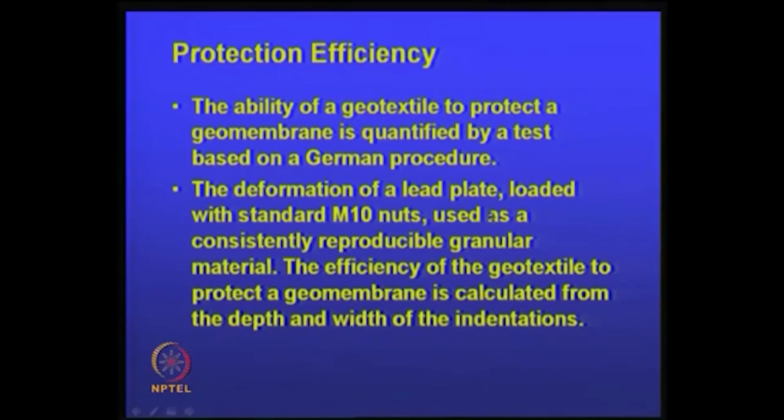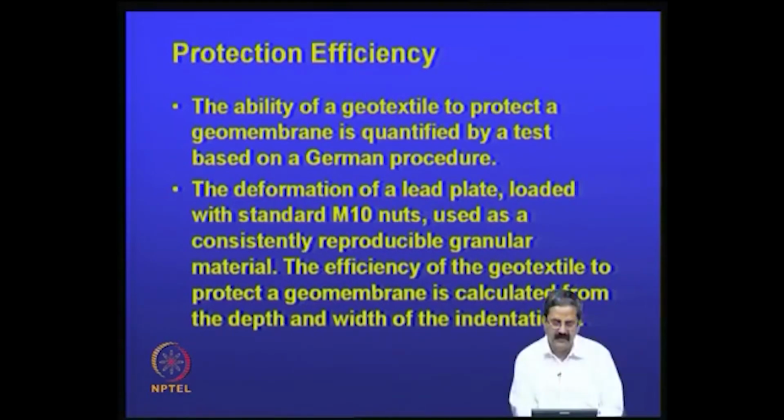Then there is another test called protection efficiency. Protection efficiency is the ability of the geotextile to protect a geomembrane. It is quantified by a test based on a German procedure. In fact, I was working in the laboratory in Germany where they developed this method.